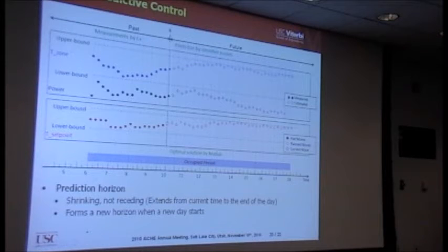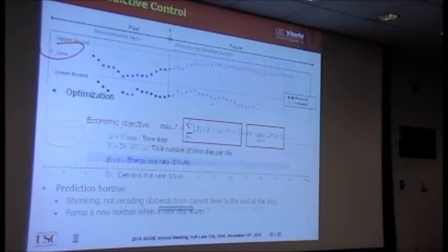Now for the closed loop model predictive control, we're going to do this. We're going to have the zone temperature as something we want to control, and the set points of the zones are something we change, okay, and we manipulate the zone temperature set point, and then we check the power consumption as an output, and then we minimize the power consumption for a particular objective.